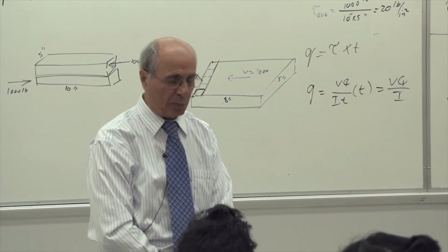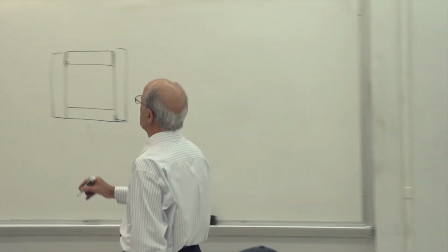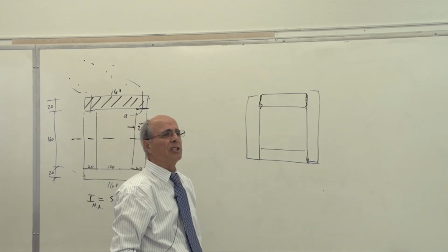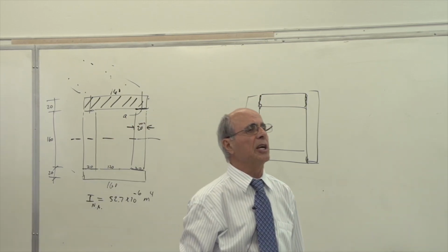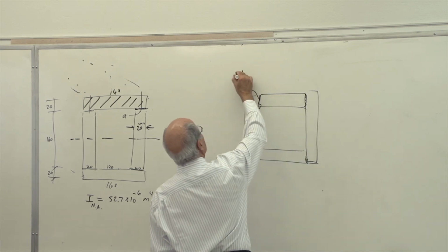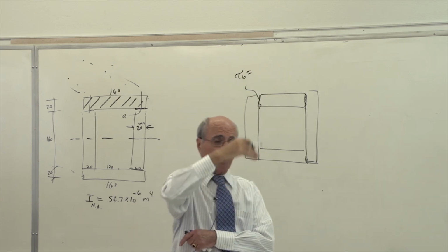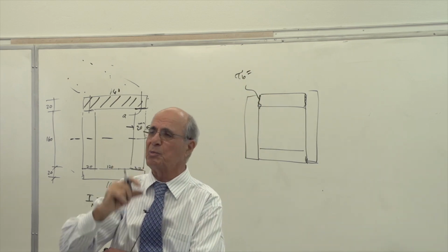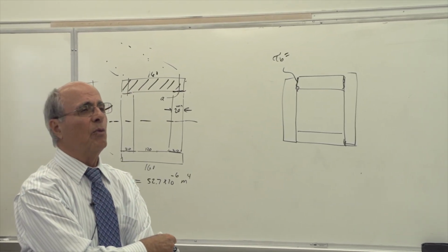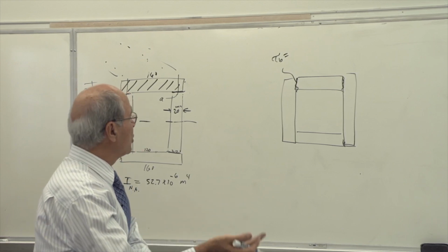Actually, when you put the nail there, it's obvious. If I ask you to calculate the shear stress here and the average shear stress there, they are different from each other. Correct? So if I ask you to calculate the shear stress tau there, on average, how much shear stress do I have there? Shear stress keeps changing from top to bottom, and this is a small quantity, so I can average it. What do you cut in order to understand? Remember, you need a Q, correct? Where is the Q? Where is the t?